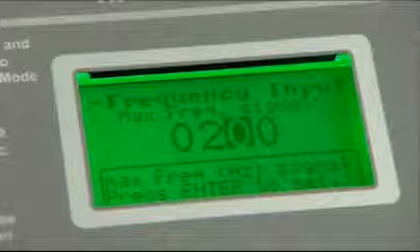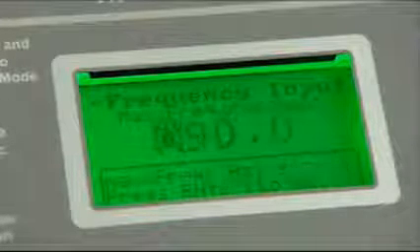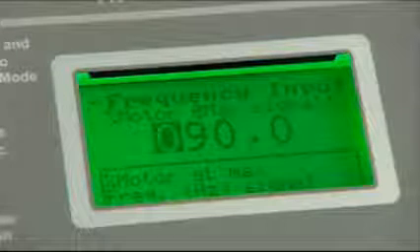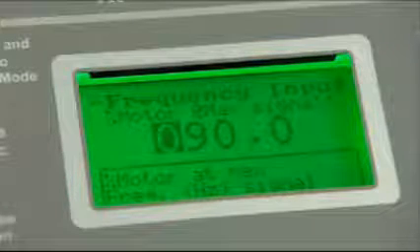Input a frequency value to define a high point on the slope. Input the percentage of motor speed required at the high frequency value. Note that the pump output may be either maximum or minimum at either the high or low frequency value. Exit the menu system.